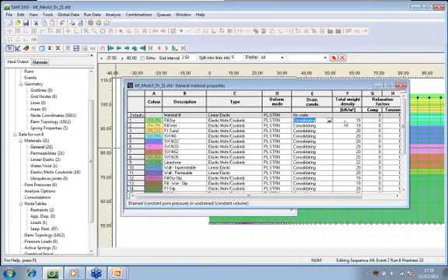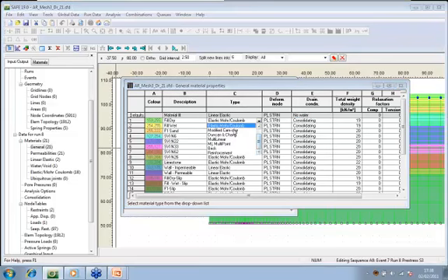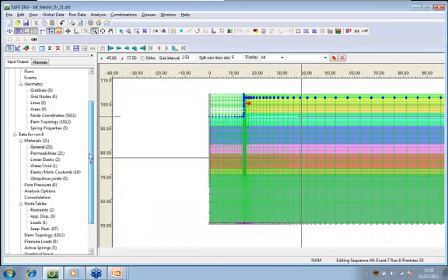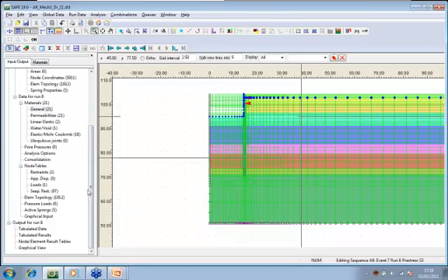So we've got different problems there. I can specify properties for my soil. As I previously mentioned, elastic Mohr-Coulomb is popular, but we've also got brick, modified Cam-Clay, Duncan and Chang. So there are a number of different types of models here that we could use for the materials. That'll just give you a quick demonstration of the inputs and how that works.